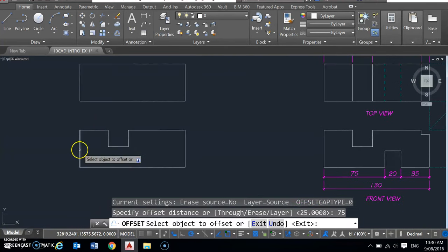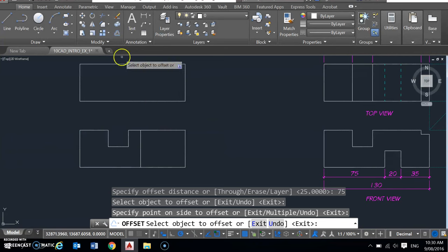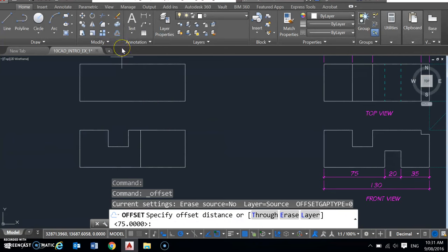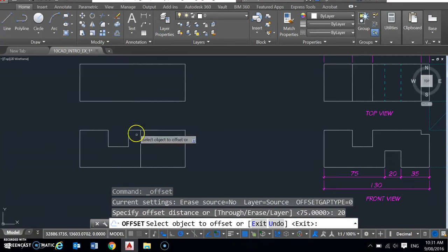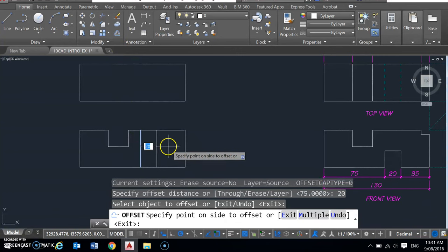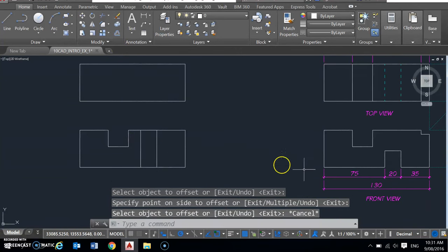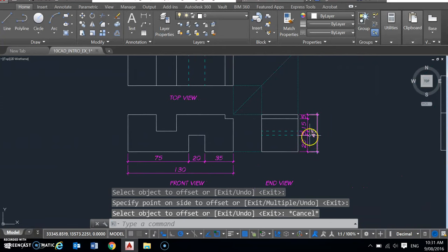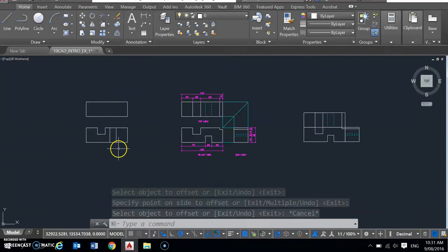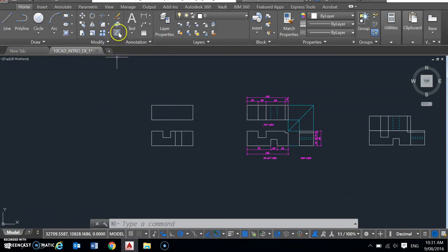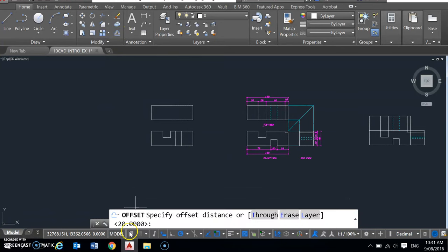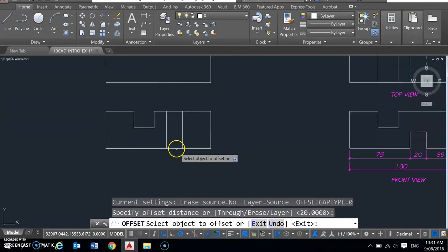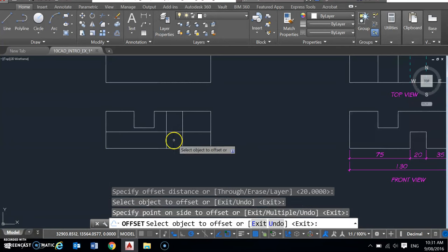I'm going to go back from this end, and I'm going to offset there, and then I'm going to go back and offset the opening, which is 20 mil, enter, offset again, escape, and now the height of it is 20 mil. So once again, I'll offset 20 mil. Now if I click on offset, you can see that it's already set to 20, so I don't need to do anything except press enter key to confirm I want to offset 20 mil, and then click.